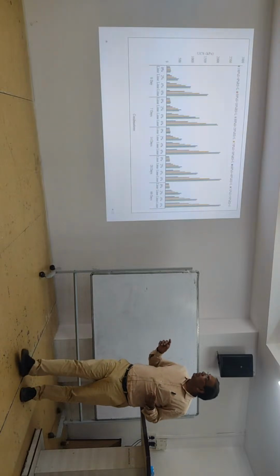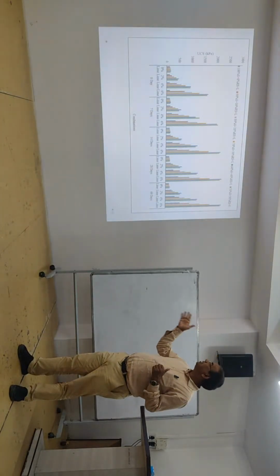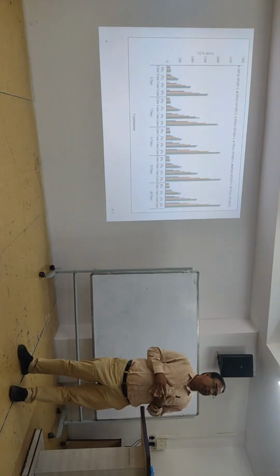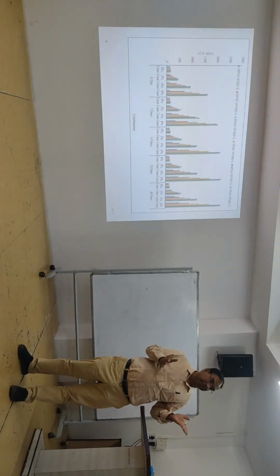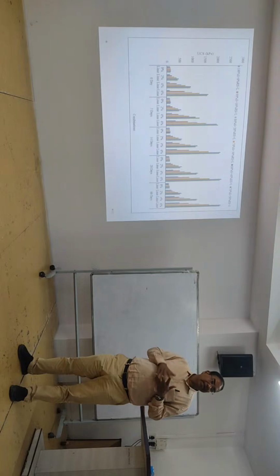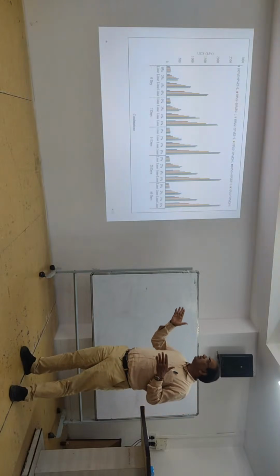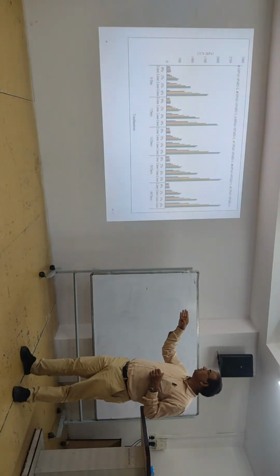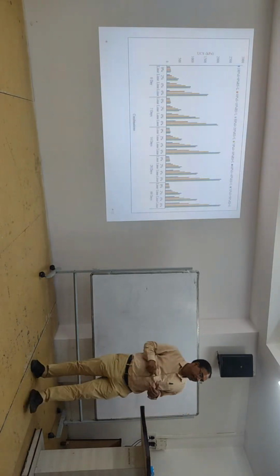These are other properties. UCS means unconfined compressive strength also we are getting, as you can see, improved at 7 days. So these are different measurements, like when you do the cube test for the concrete, we do cube test, then flexural strength test, different tests. After the CBR test, that is shear strength we get. CBR test means we get shear strength. UCS we get other strength. So flexural strength. So you can see here that we are also getting around 2000 and above kilopascals.